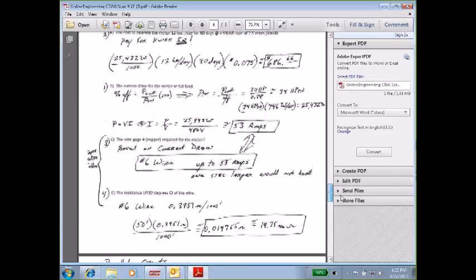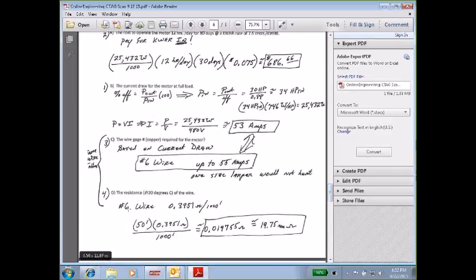Okay, now this Part D, that's straight from the wire table. They have to look up on the wire table, and the wire table is always listed in ohms per 1,000 foot. So then they're going to have to set up a little ratio, 50 feet times the ohms per 1,000 foot. And we come up with a very, very small number.